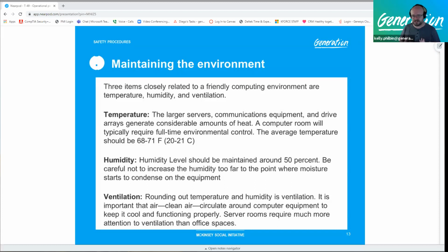To make circulation run more efficiently within server rooms, they create a cold aisle, where that entire aisle is nothing but the front of machines, and then the next aisle will be nothing but the back of machines, so that you're able to draw in the cold air and push out the hot air. It makes for much more efficient airflow and maintains the temperatures of the server rooms. So they do that by creating hot and cold aisles.